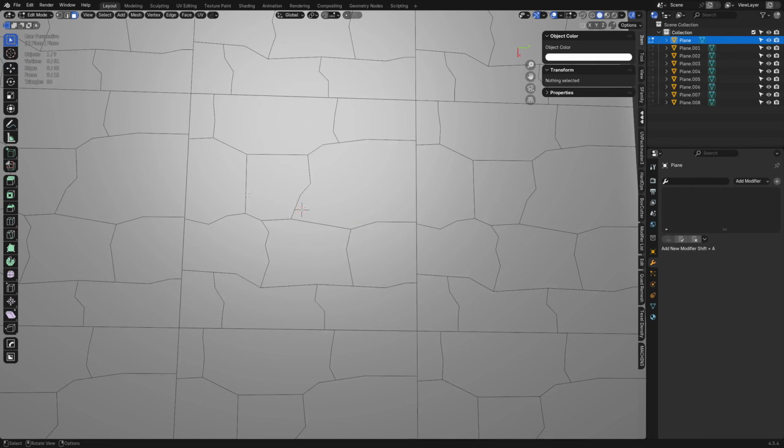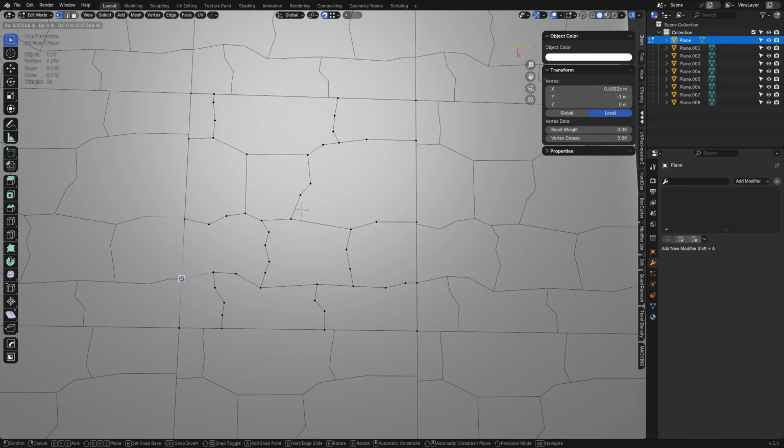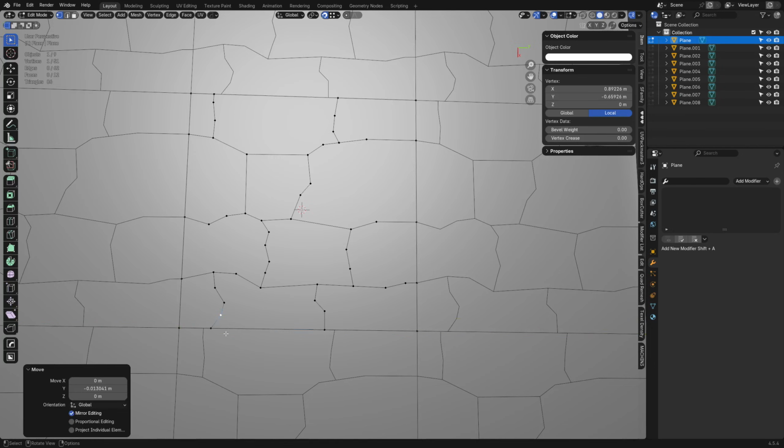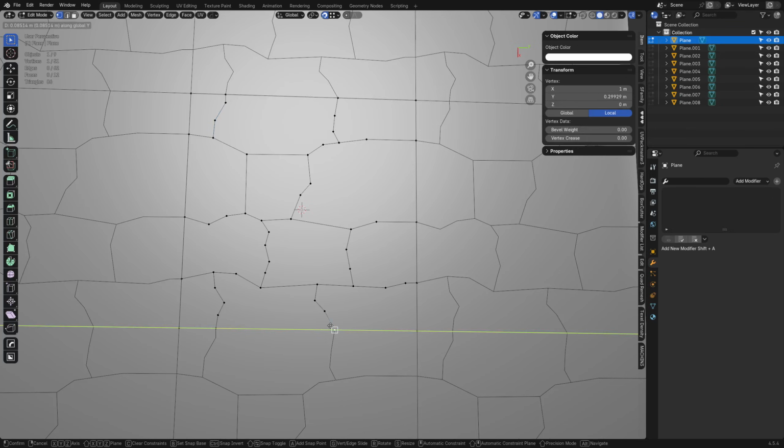So you're going to create your setup here. We're going to use vertex snapping on for now. And we're just going to press G, and these should snap into place like this. Okay. And we can do this one at the bottom. See, we don't want to move it like that, right? So press G and Y. Move that one over a little, maybe. Straighten it up a bit. Then you can take the top one and snap it to it and tweak this one now. You get a nice look, more or less.